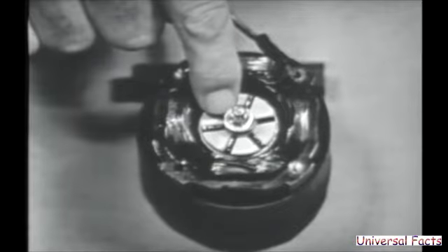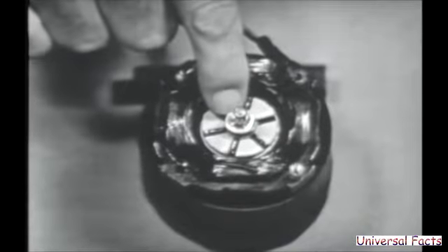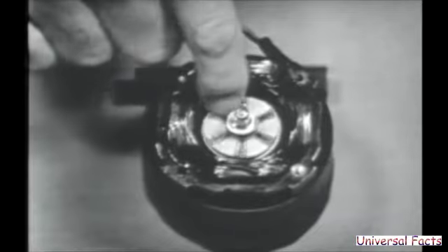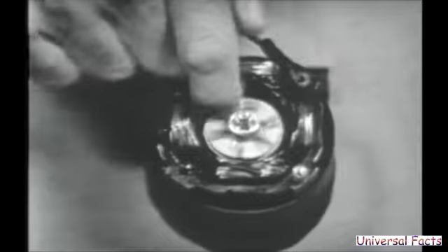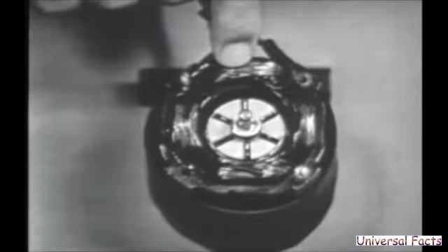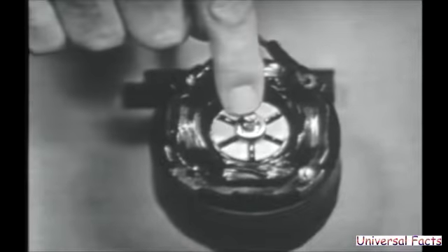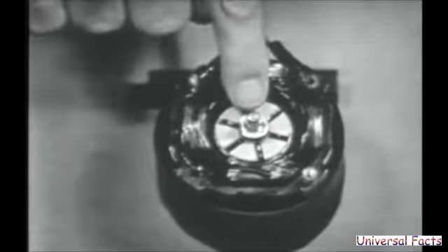Right. Okay, so the rotating magnetic field then induces a voltage into the conductors of the rotor, causing it to become an electromagnet. It exhibits a north and a south pole. The rotor turns at some speed determined by the load, both internal and external load. Now, the difference in speed between the rotor and the magnetic field is called slippage. All right?